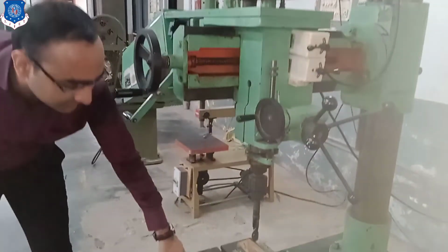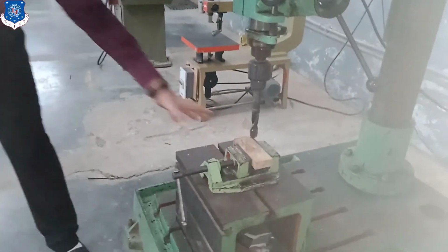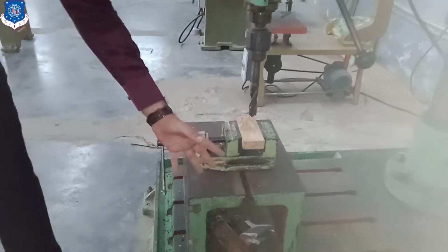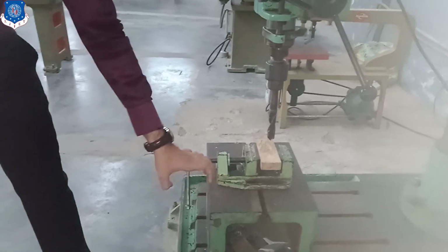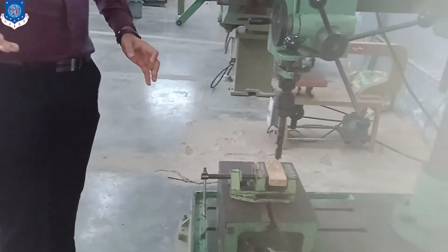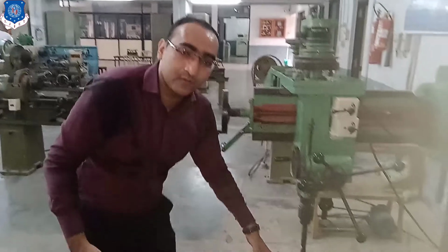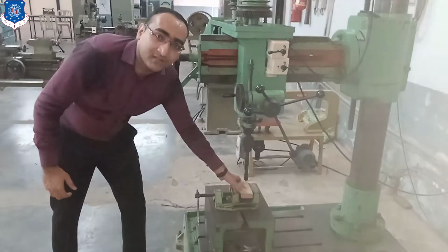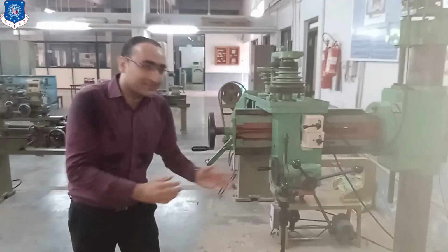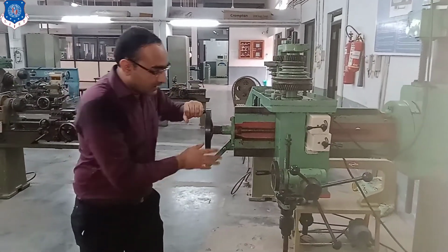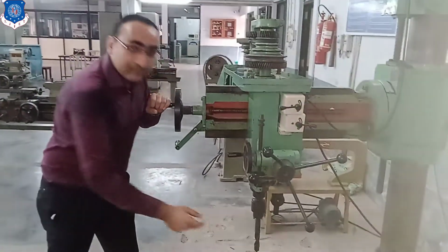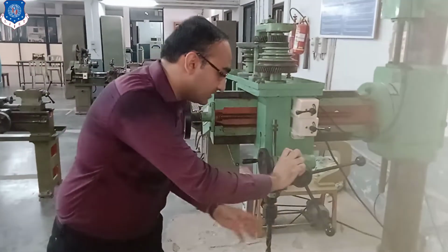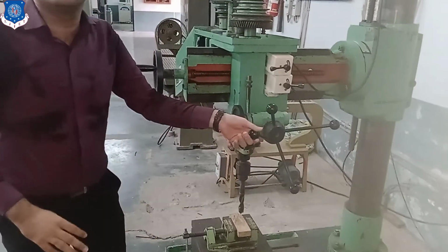And over here you can see, this is the work table on which we are placing the workpiece. This is the machine in which your work table is always kept on the base. Otherwise, as we have seen in the sensitive drilling, it is hung on the clamp. But over here you can see it is always on the bed, and on it there is a vise, in which we have inserted our workpiece. So we can adjust the tool with the help of this movement, and wherever we require a particular hole we can set the tool over there, and just by moving this it can go in this pattern.